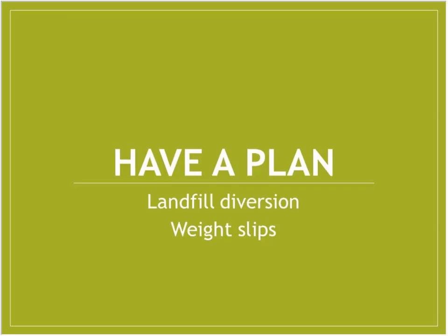And then have a plan right before you start your new construction or remodeling process. Get an idea of how much waste is going to be generated. Do some research locally on where that waste can go when it's done, and how to keep it out of the landfill. You can work with local waste management organizations that will get you weight slips, which can be beneficial in many ways, either for green building certification or just for something that you can tout, where you can say, hey, projects that we do have a 90% landfill diversion rate.